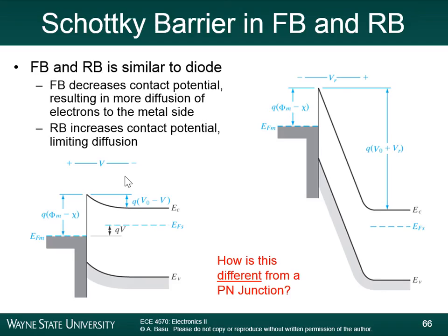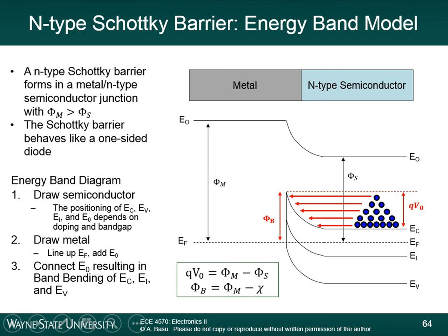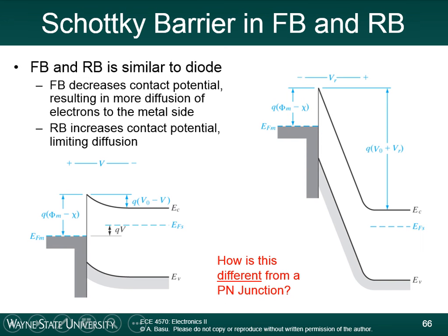Another thing you can interpret from looking at this band diagram. So we have this barrier here, and when the barrier reduces, the electrons can dump over to this side. Okay. However, can the electrons go in the opposite direction? Look at the device in forward bias. In forward bias, you've reduced this potential barrier so the electrons can go from here. An electron here could find some empty states here, so the electron just drops down here.